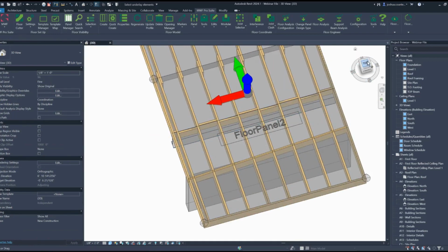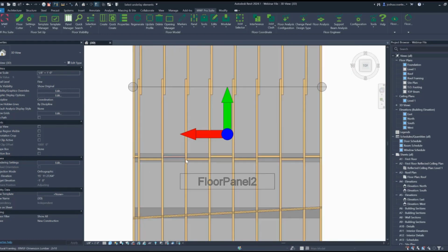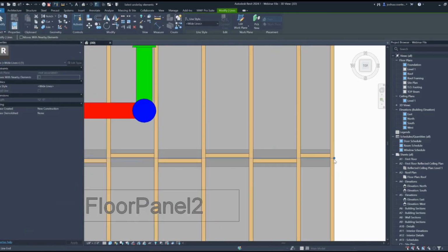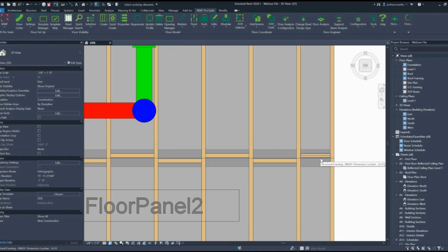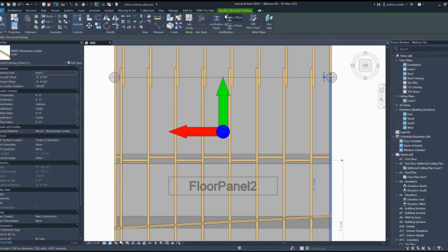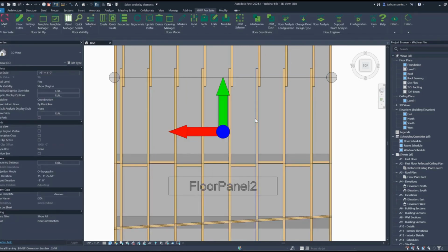And now if I go to my top view, I believe I set a 1-inch offset with the stagger, and it's aligned to the center of this I-beam below. I could move the line if I prefer. If I want to add a diagonal to it, I can do that too. Just keep in mind, as you make those modifications, regenerate your panel.